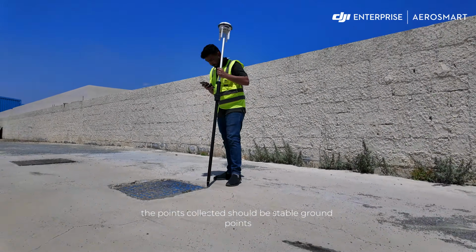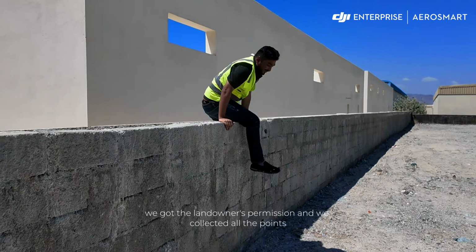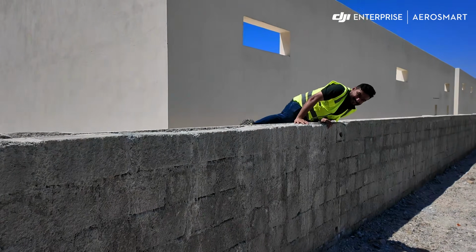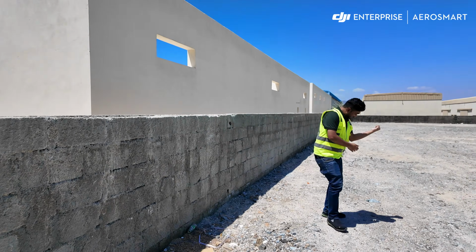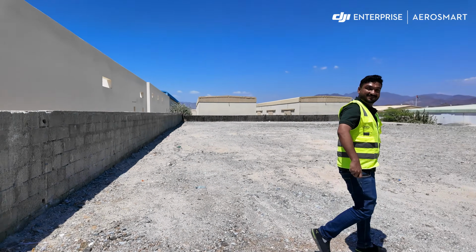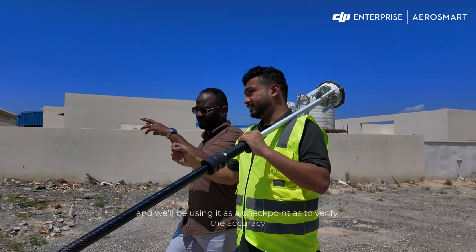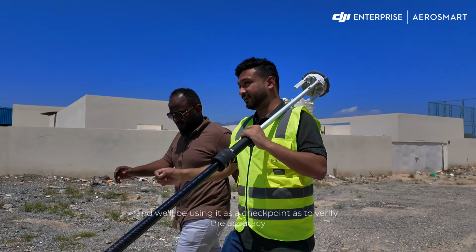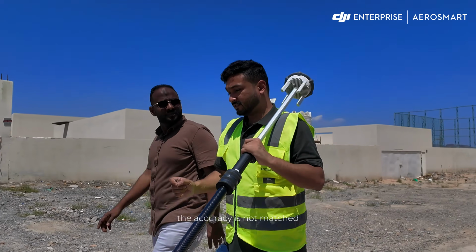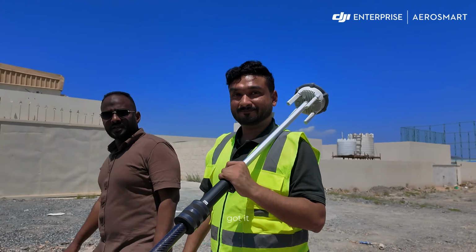The points collected should be stable ground points. So with a few hurdles, we got the landowner's permission and we collected all the points. How's it been, bro? All good. And we'll be using it as a checkpoint to verify the accuracy. If the accuracy is not matched, we'll be using ground control points to correct the checkpoint. Yeah, got it.